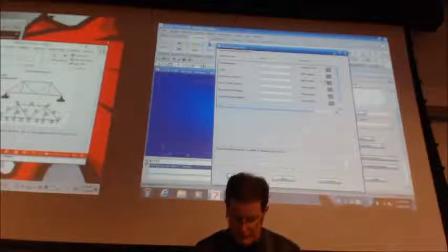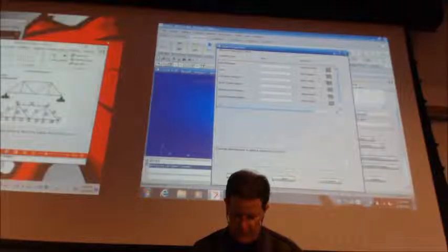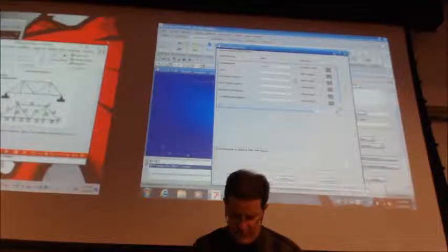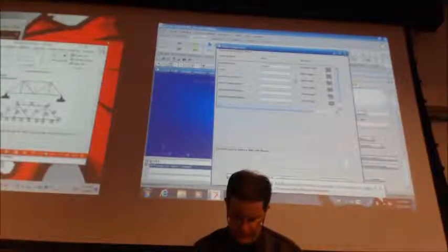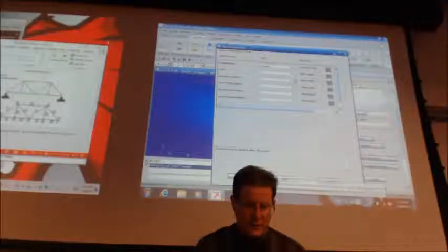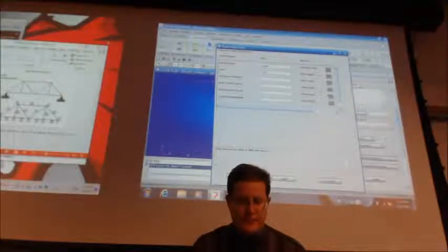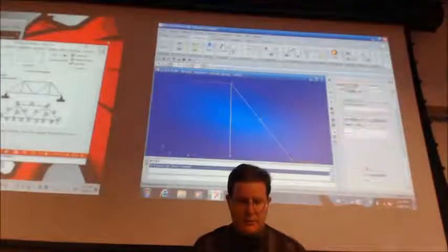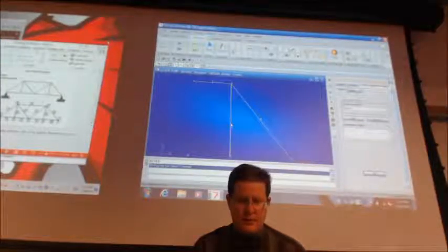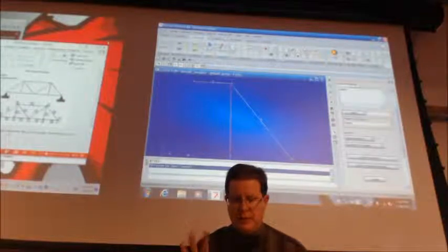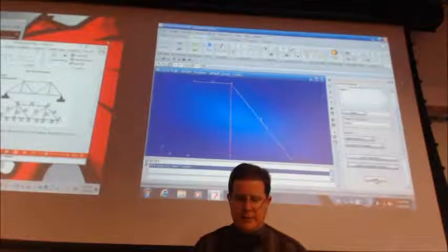So this one, element 2 is still aluminum, but now 1 square inch. It's 1 square inch, right? Okay, select, put it on element 2, add, okay. And I want to apply that.